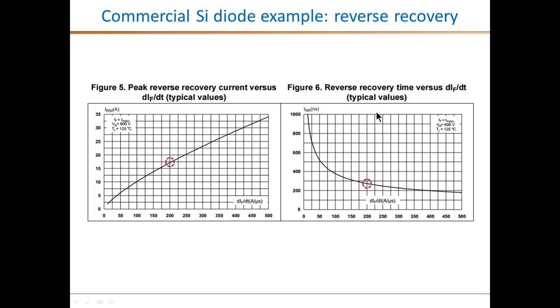And then looking at the reverse recovery time, again for the same dIF/dt, the reverse recovery time is closer to about 280 nanoseconds, which is actually quite high for high frequency converters. So in conclusion, we can say that the design of these silicon pin diodes is really a trade-off between the on-state drop and the reverse recovery characteristics. So in the next part of the video, we will look at the silicon carbide Schottky diodes and understand how they achieve this better performance.